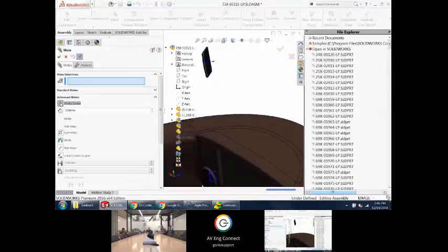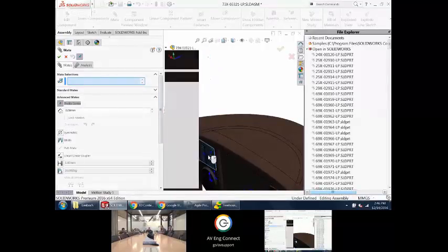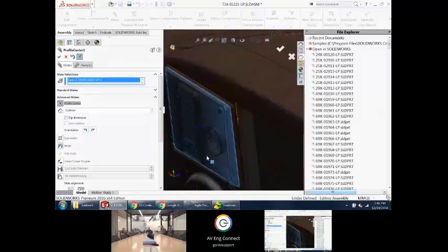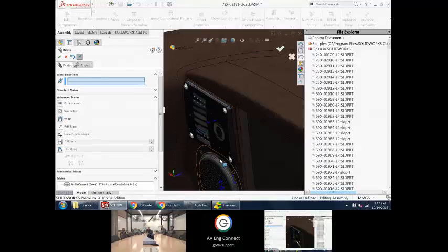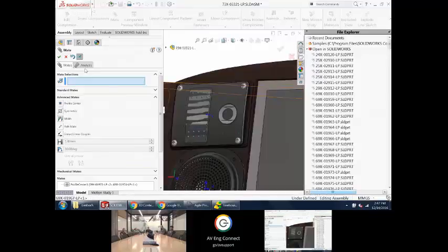They've done this profile center where if I pick those two faces, it just centers them up. So if you've got a rectangular face that you're mating a rectangular item to, it'll just center it in that rectangle. If you're doing a circular to circular, it'll just center them right on top of each other. It is just like a width mate, except now it's got to calculate geometry every time it solves that mate, but it's really nice for putting stuff smack down in the middle of something. Just like that. It would have taken me 3 mates at least, and this got the job done in 1.